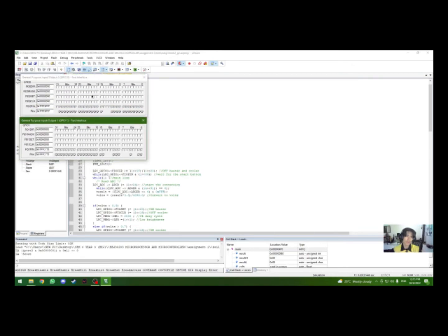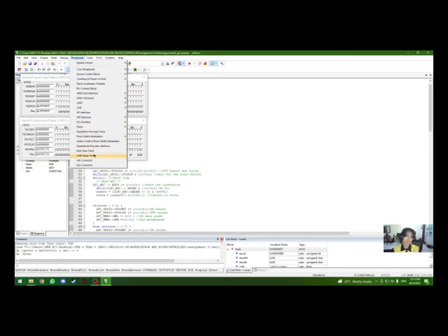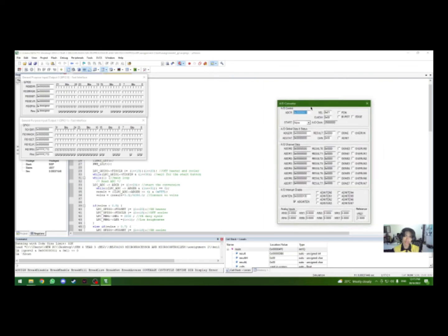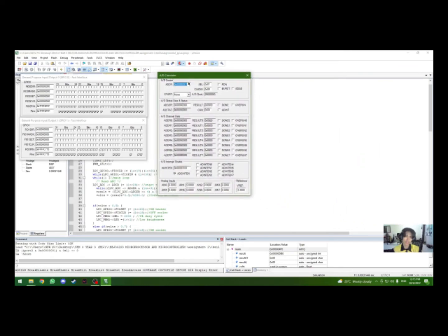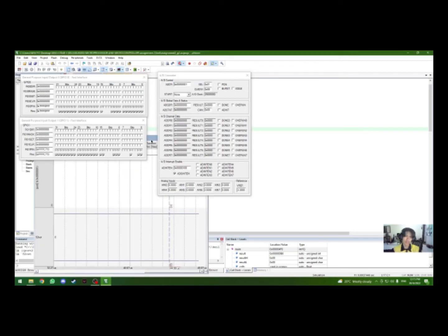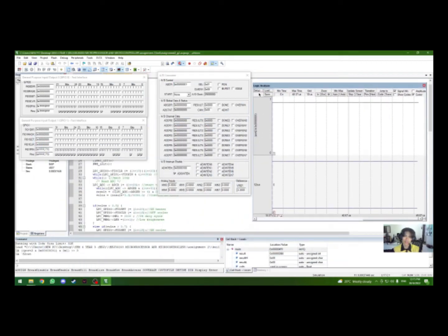Basically, once you have these two GPIO ports, you can also take the AD converter out, which is the analog to digital converter, and you can set up the logic analyzer right here as shown. For this one, port 2 is the output for the LED. The first port is going to be the PWM, and this one is going to be the address of the PWM.